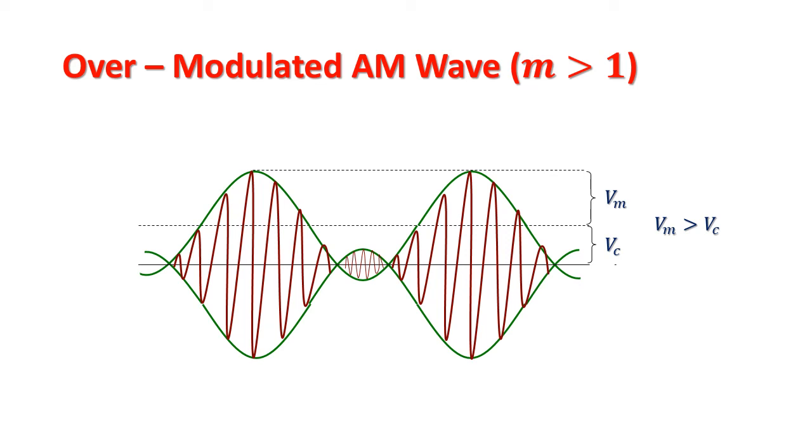When overmodulation occurs, the carrier experiences 180 degrees phase reversals where the carrier level would try to go below the 0 point. The 180 degrees phase reversals give rise to additional sidebands resulting from the phase reversals. These sidebands caused by the phase reversal extend out, in theory to infinity, and can cause serious interference to other users if not filtered.